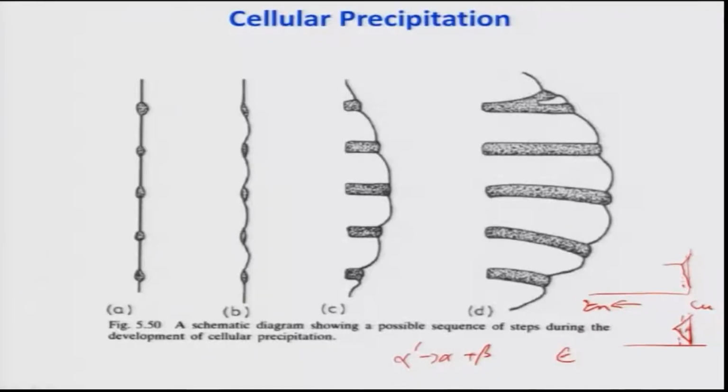This is eta basically. So, this will be epsilon plus eta. Precipitates of epsilon will form in the matrix of the eta. This is what is routinely seen, and this eta is basically a solution of, sorry, this is zinc, this is not copper, this will be different because this is zinc, an HCP solution. But this happens by diffusion control.